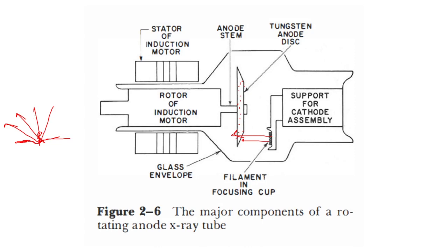This is not what we wanted, right? We want the target anode to work for a longer time. We do not want to distort the surface of the target anode. Because of repeated exposure of the target anode to electrons, these electrons hit the target anode with a high amount of velocity and high kinetic energy. These will cause pitting and roughening of the anode surface.